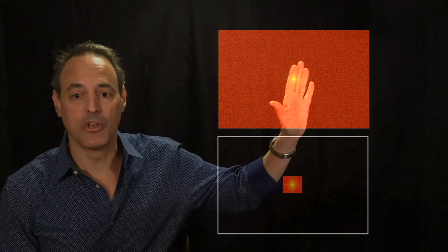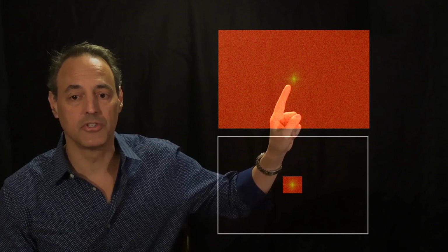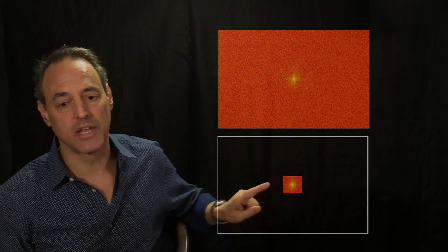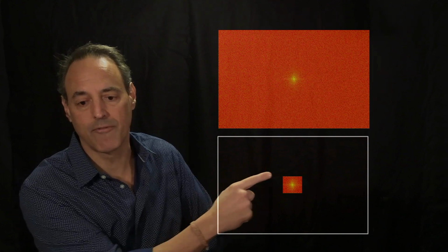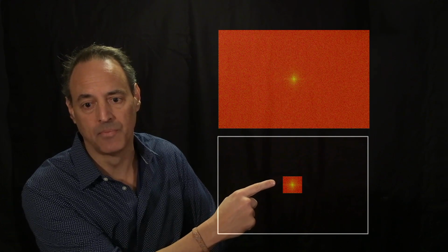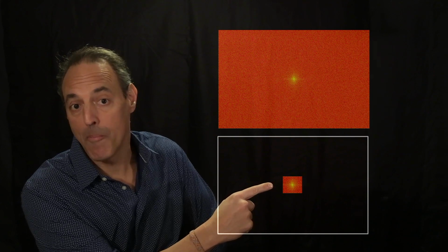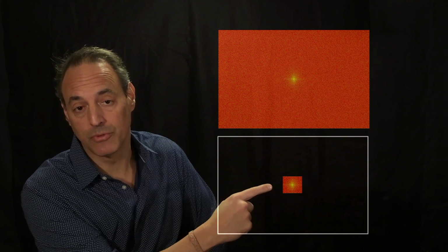I start off here with my noisy image in the Fourier domain, and so most information is here. And of course, I've got noise everywhere in this. So what I want to do now is take a small region where most of the information is. And that's right here. Okay, so take that information. Here it is. And then what I want to do with this is multiply it by this mask. So it's zero everywhere. In other words, I zeroed out all the space around it except for this little box where I'm keeping just that. This is my notch filter, my low pass filter that's only keeping those frequencies that you see in that little box. I'm throwing everything else away, multiplying by 0 because mostly it's noise.